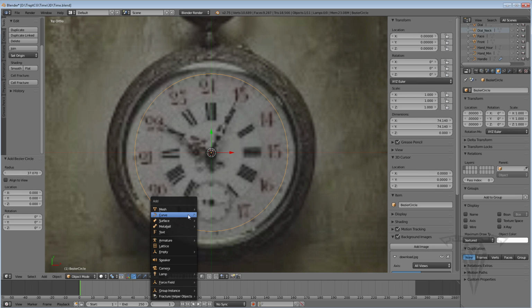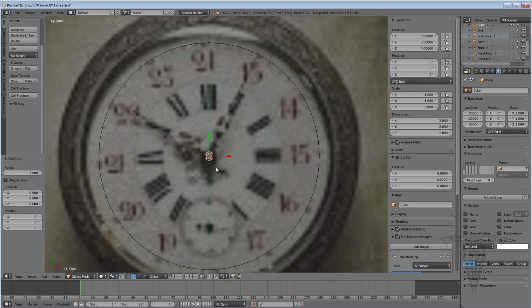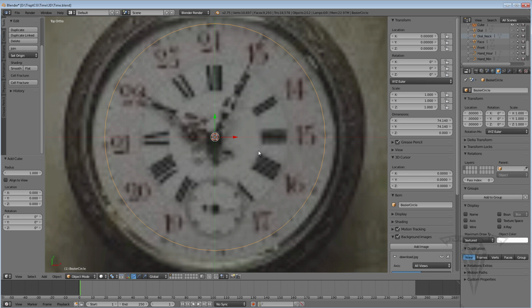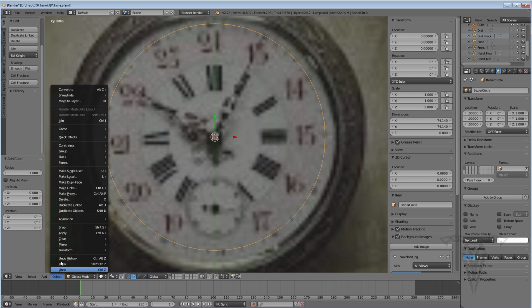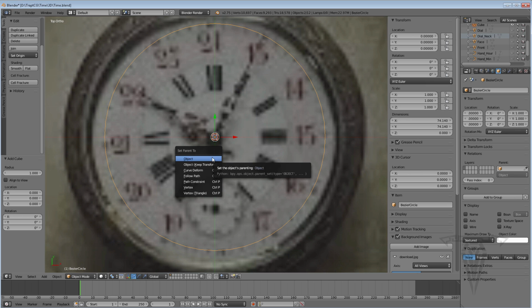So let's go ahead and hit Shift A again. We're going to create a box, a cube. All right, so we're going to link the box to the path, and it's not combining or joining it, it's linking it. So I'm going to select the box, select the path, and so it's a child to parent relationship, and this is the direction we want to create it. Shortcut key is Control P on the keyboard, and we're going to do object, but just to show you where that's at, again, if you don't remember your shortcut keys, if you go object, parent, there's lots of options, but we're doing the object parent right here. So Control P and object.